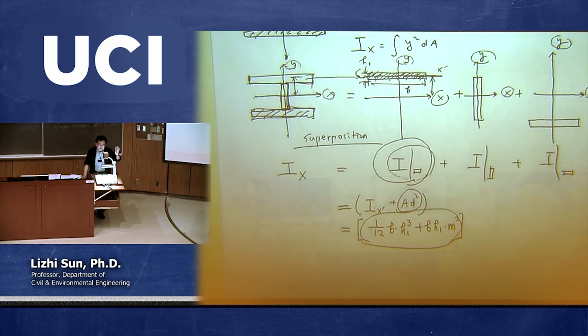One of the reasons in reality they build a beam with a curve is because they want to minimize the stress concentration. That's a different issue. When you make something with a curve, you decrease the stress concentration. If you look at the airplane, all the windows are some kind of circle instead of a rectangular shape, right? Because those corners would create stress concentration. But that's a different issue. It has nothing to do with the moment of inertia, but it would affect something else.